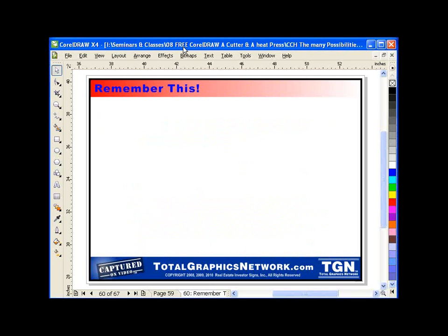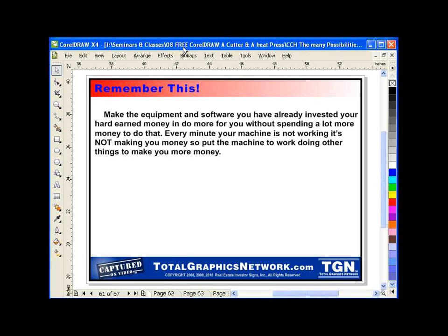We talked a little bit about bags earlier. I've had people put tennis shoes in a heat press. I've had people do all kinds of crazy stuff in heat presses. My suggestion, if you're going to do something like this, is to always test first, and don't forget to use Teflon sheets on top of what you're doing and underneath what you're doing, just in case something screws up so you don't have to clean that heat press.